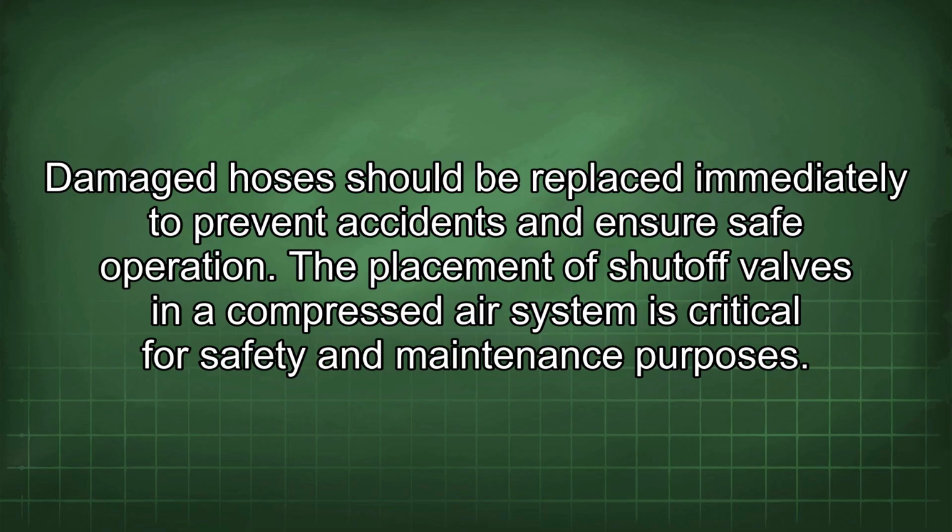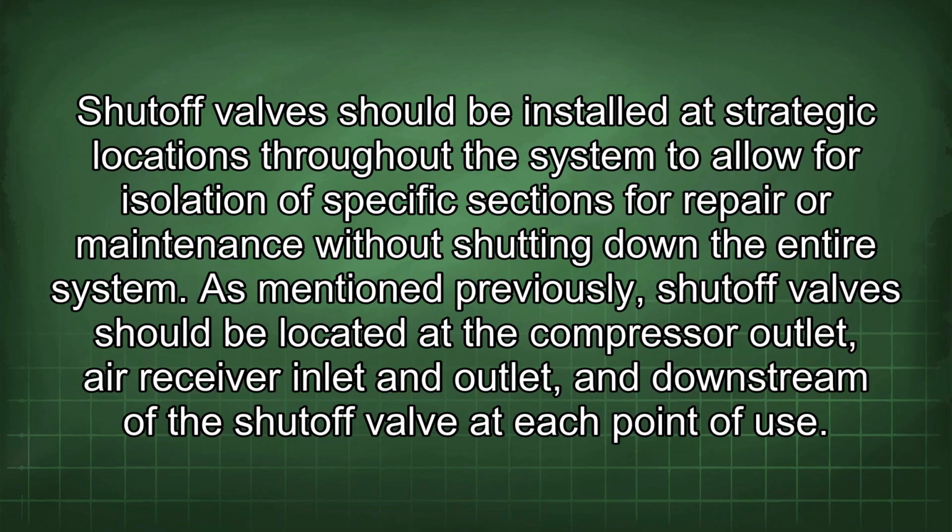The placement of shutoff valves in a compressed air system is critical for safety and maintenance purposes. Shutoff valves should be installed at strategic locations throughout the system to allow for isolation of specific sections for repair or maintenance without shutting down the entire system. As mentioned previously, shutoff valves should be located at the compressor outlet, air receiver inlet and outlet, and downstream of the shutoff valve at each point of use.